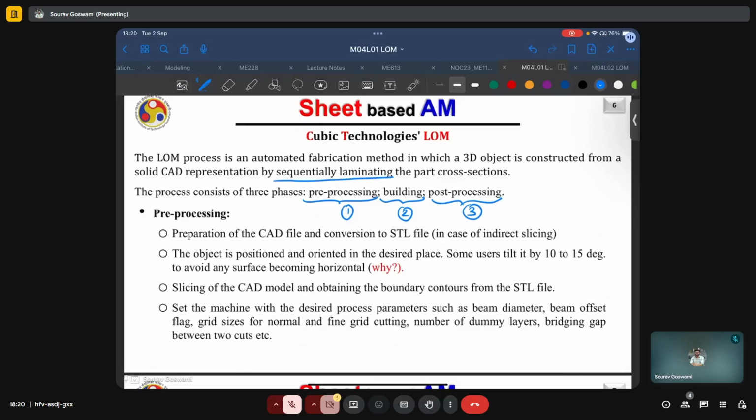And then, when we slice such an approximated geometry, in each layer the contours that we end up with will not be smooth curves, but rather some approximated curve in the form of a multi-sided polygon.